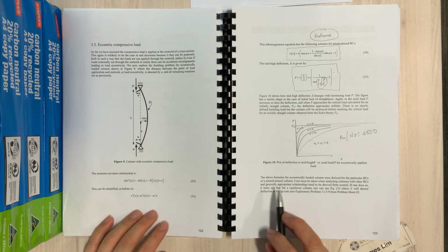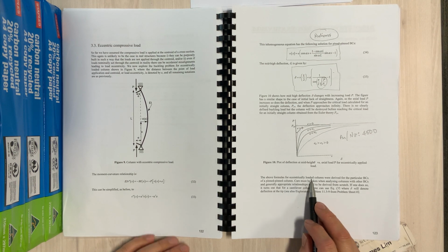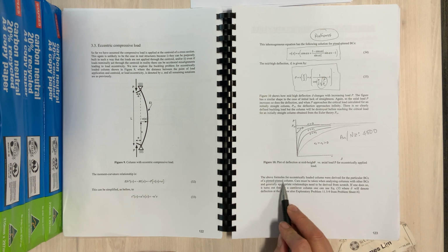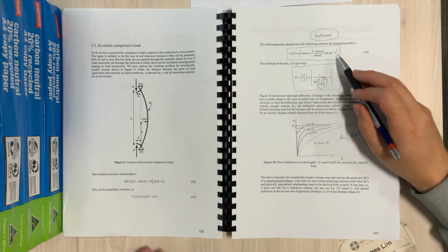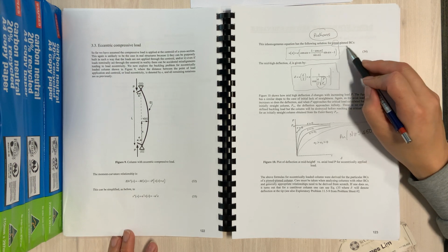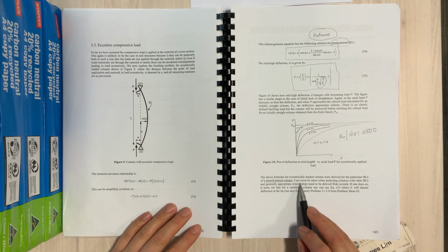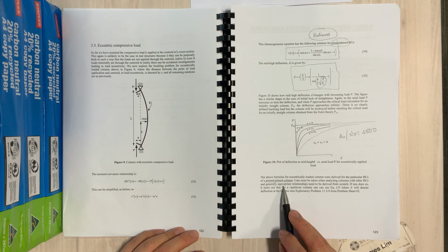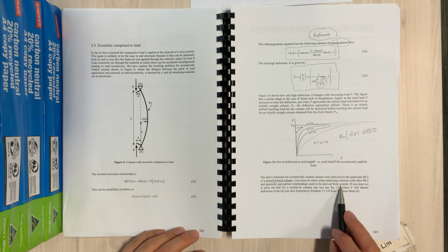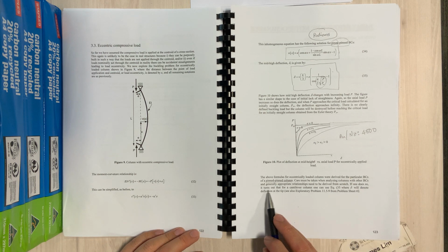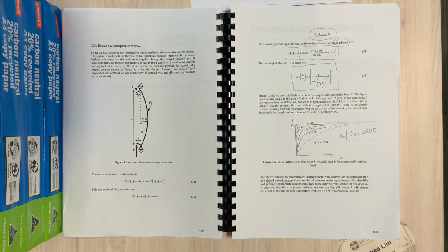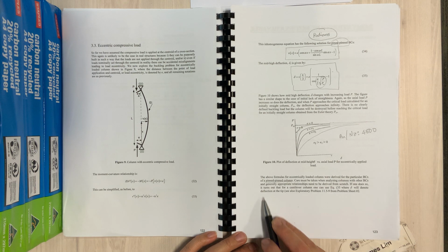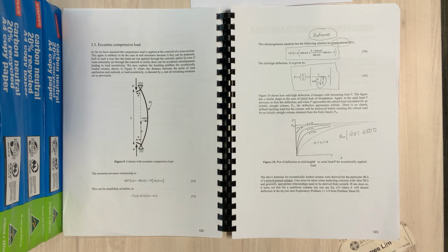Anyway, let's go on. So the above formulas for eccentrically loaded columns were derived for the particular boundary conditions of a pin-pin column. So same as before. So this is just pin-pin, as is emphasized there. Care must be taken when analyzing columns with other boundary conditions, and generally appropriate relationships need to be derived from scratch. If one does so, it turns out that for a cantilever column, one can use equation 35, where delta would denote the deflection at the tip.